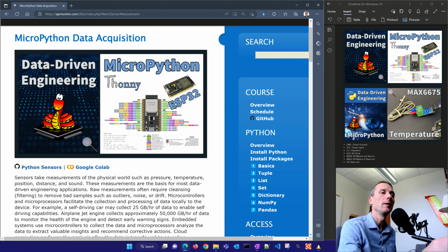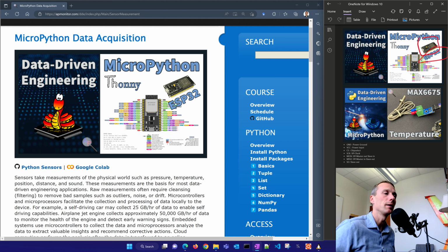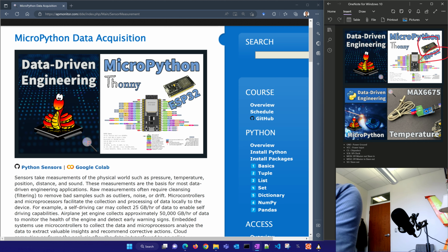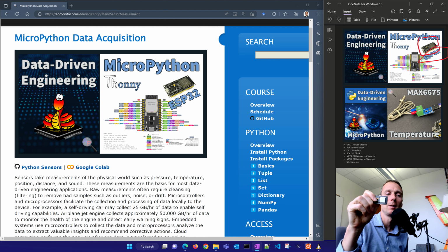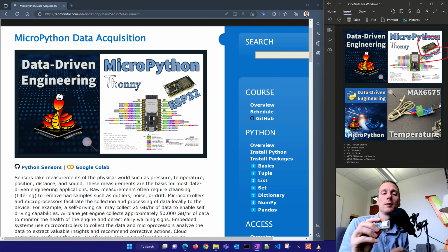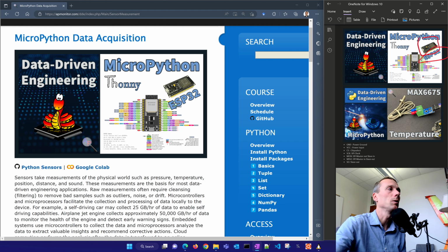And so we're going to use this little device right here, and I'll go ahead and show it to you. I'll plug it from my computer. So here's a little ESP32, and it has Wi-Fi and Bluetooth that you can use to develop some type of Internet of Things, like an IoT device. And it already comes with the pins here, so it's very easy to connect. We're going to talk about how to connect this with an SPI interface and be able to measure something like temperature today.